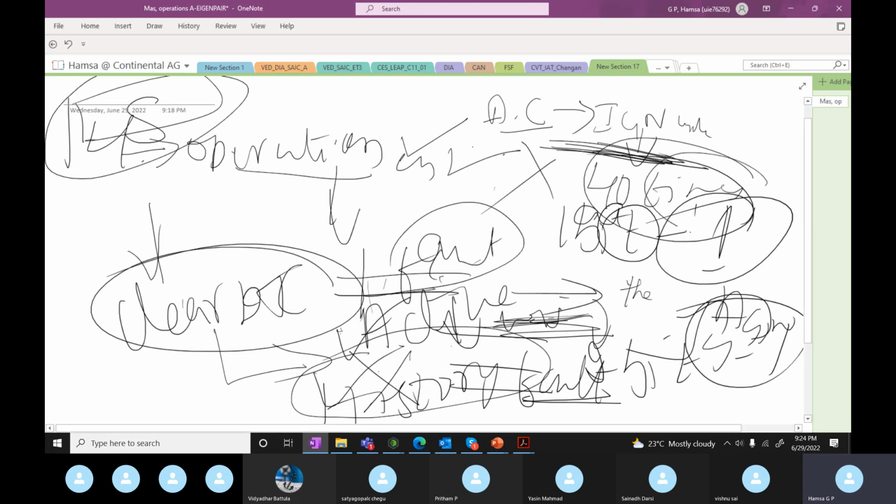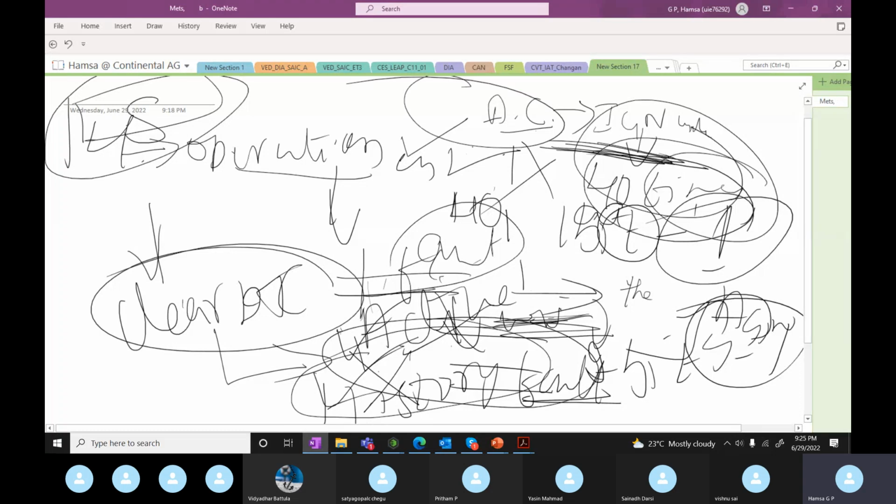The ignition cycle: how many times you have turned the car on and off. This counter keeps incrementing with every turn on, turn off. Once the counter has reached 40, the DTC stored in the memory as a history fault will be automatically removed. That is called the aging counter.